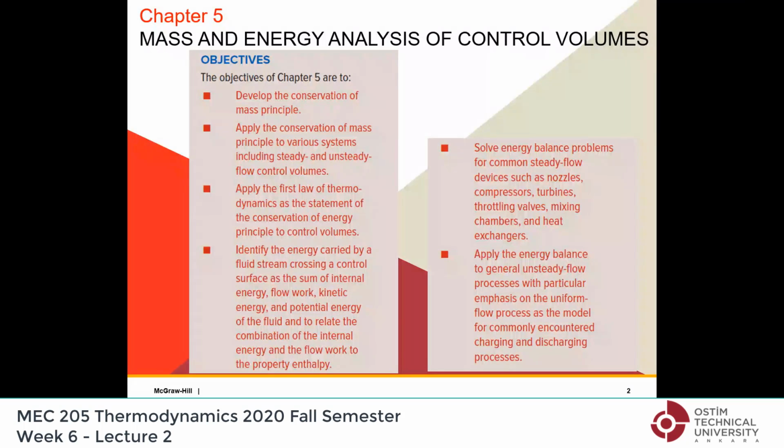Then we will concentrate on steady flow systems, like nozzles, compressors, turbines, throttling valves, mixing chambers, and heat exchangers. Steady flow means no changes within the device, but the interactions are obviously different. If the operation is steady, with no change with time, how do we deal with those? Most systems in engineering are that way, so we will show how to analyze them.